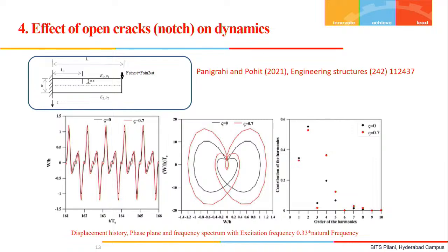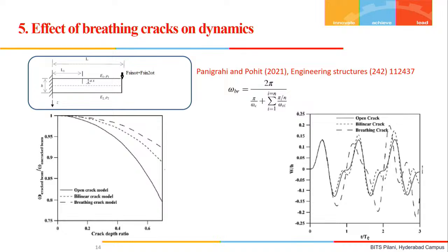The modal parameters of the structure are going to perform differently, and the steady state response coming from the excitation will be significantly different. So this is one takeaway that structural engineers can take for structural health monitoring purposes. The second thing is the response of a breathing crack, modeling in the dynamics of the beams.